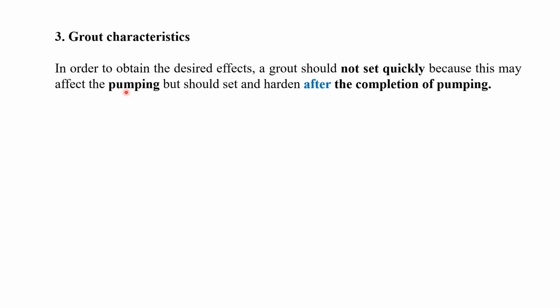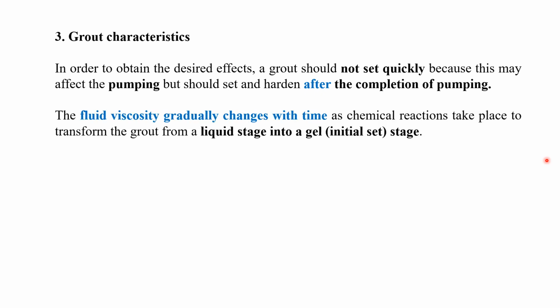Otherwise we cannot go to the deeper depth, but it should set and harden after the completion. Once we complete our required depth of the grouting, then only the hardening should start, right? So grout characteristics should be like that. The fluid viscosity gradually changes with time as a chemical reaction takes place to transform the grout from a liquid stage into a gel stage or semi-solid stage.